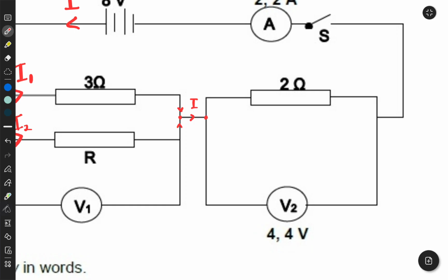Remember, the reason for that is because a voltmeter has a very high resistance. Current doesn't like too much resistance, so it wants to flow in the path of least resistance. That's why whenever we connect a voltmeter, we connect it in parallel to that resistor whose potential difference we want to measure, right? So there's nothing that will flow to that voltmeter. This is just the total current flowing through the 2 ohm resistor. Then it goes all the way there, and then it recirculates again.